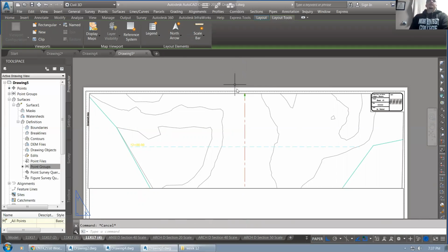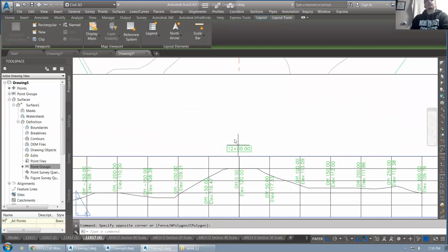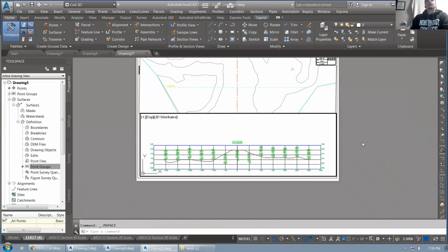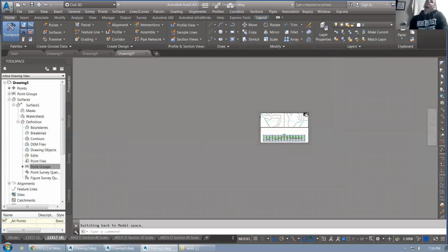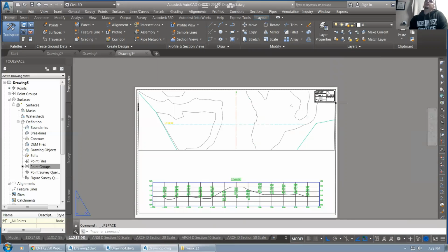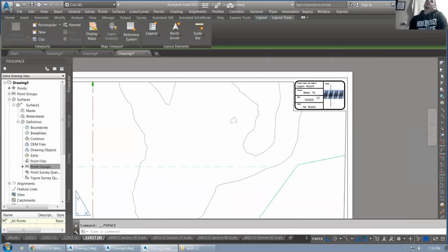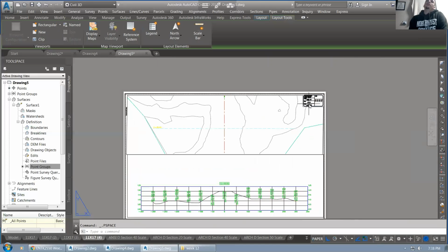Yep, and that's pretty much it. I mean, you just do that. It's probably best to add your scale bar and north arrow now and then make a copy of this guy. You might want to actually center this bottom one, or move your viewport down on the top, whatever you want to do. But yeah, go ahead and update your little title block here to say station 12 plus pair, 12 plus 00 here, final. And then the scale would be 30, right? So scale bar 30.